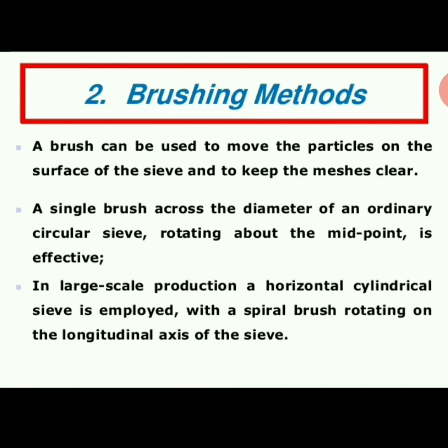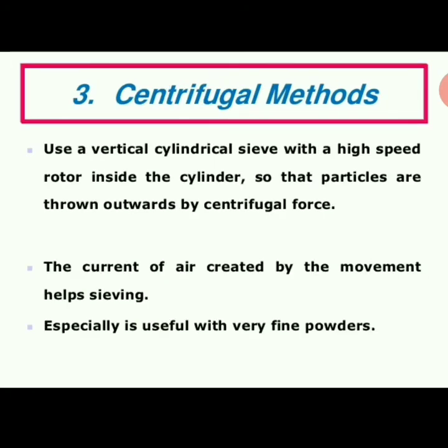देन नेक्स्ट मेथड इज सेंट्रिफ्युगल मेथड. In that a high speed rotor is fixed inside a vertical sieve so that the particles are thrown towards the sieve by centrifugal force. In this method, centrifugal force arises and it gives the proper size separation. The current of air created by the movement helps sieving and also especially is useful with very fine powders.